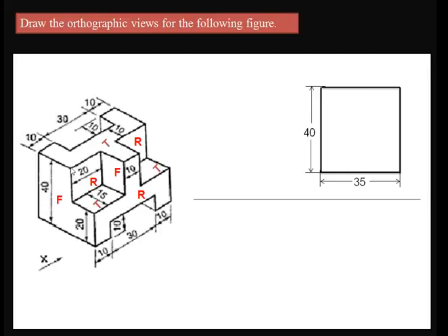First look at this edge, the top edge on the top of the rectangle we got in the front view, that is 20 mm. From this 20 mm point draw a line equal to 20 mm. Again in the front view we can see this edge also in a horizontal direction as a horizontal line which is at a height of 20. Again represent 20 mm and draw the line until it intersects the first drawn line. So like this we can see in the front view, and at the same time there are certain hidden edges in this figure.